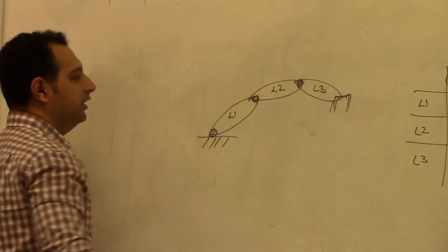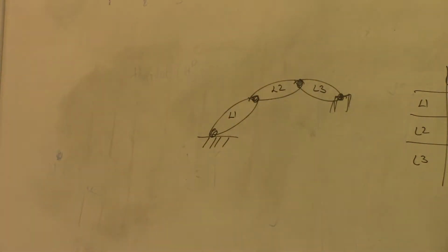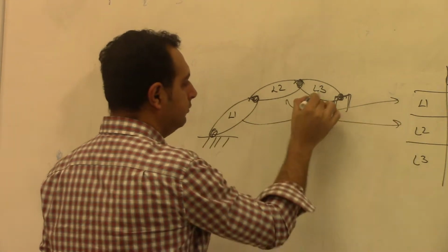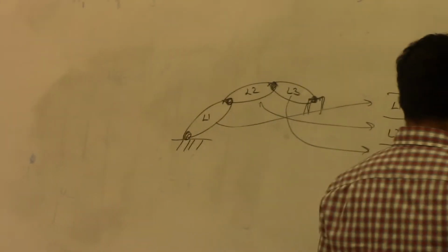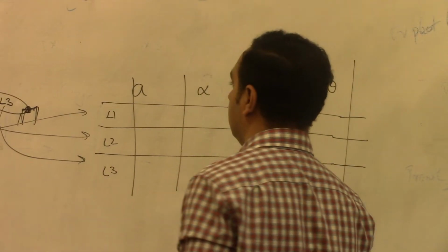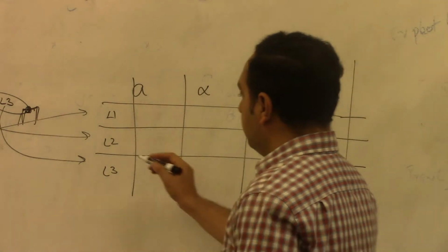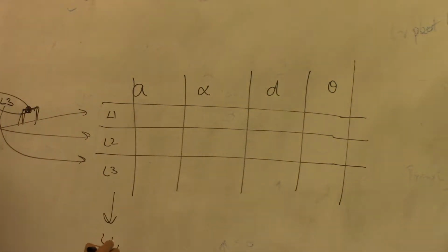In this case, all of them are flexible, they are not rigid, because it allows for motion. If they are rigid, then there is no motion, okay? There is no relative motion between the links. So what we do is, we'll define link by link, like this, right? And we will specify this in terms of a link parameter, link structure in MATLAB, and then we'll combine the links to form a manipulator. Okay, so we'll combine L1, L2, L3 to form a manipulator.